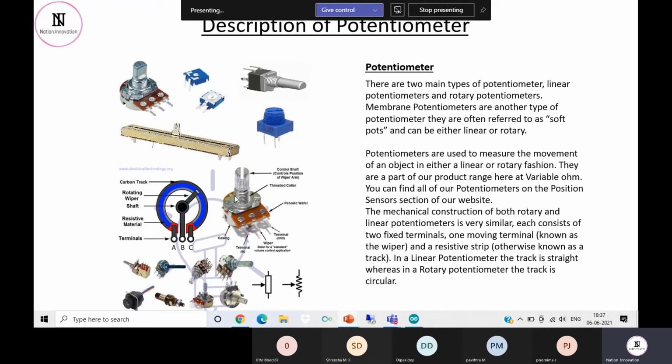Fine. And in the rotary section, with the rotation of the knob, we are going to have a difference in the output voltage. Now the main thing we want to know here is that the Arduino is neither able to measure resistance nor capacitance. It is only able to measure voltage. So with this potentiometer, we are just going to divide, or basically change, that voltage which it is going to be sensing,